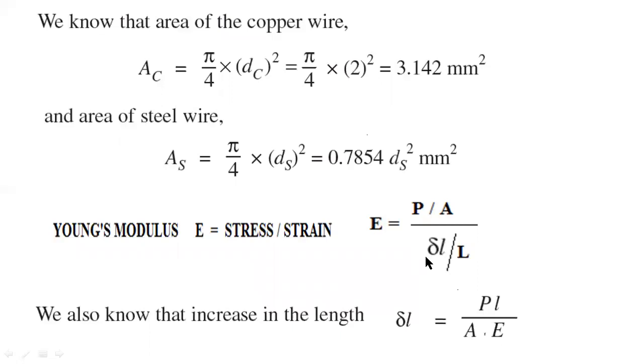Change in length is also known as extension or compression. So ΔL is the change in length and L is the original length. This is the main important formula in the mechanics of solids subject, so please all of you remember this formula.